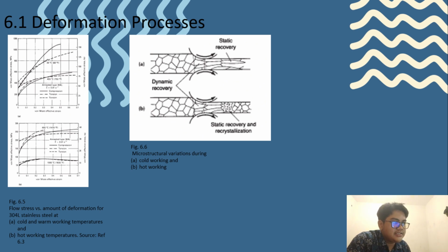Metal forming processes can be classified into two general categories. First is bulk or massive forming operations, and second, bending and sheet forming operations. Sheet forming is sometimes simply referred to as forming in the broadest and most accepted sense. However, the term forming can be used to describe both bulk deformation processes, sheet forming, and bending processes.